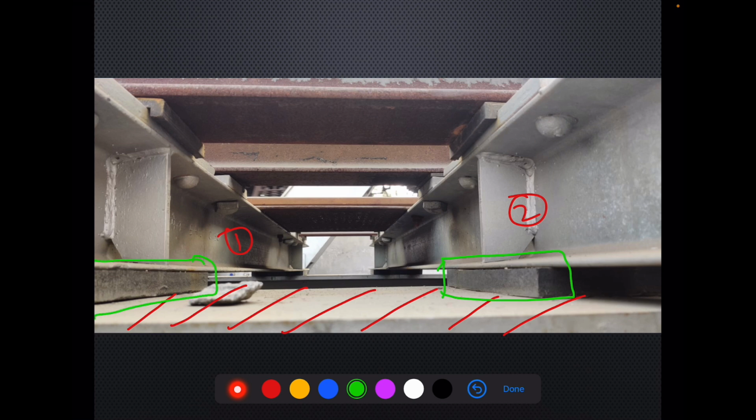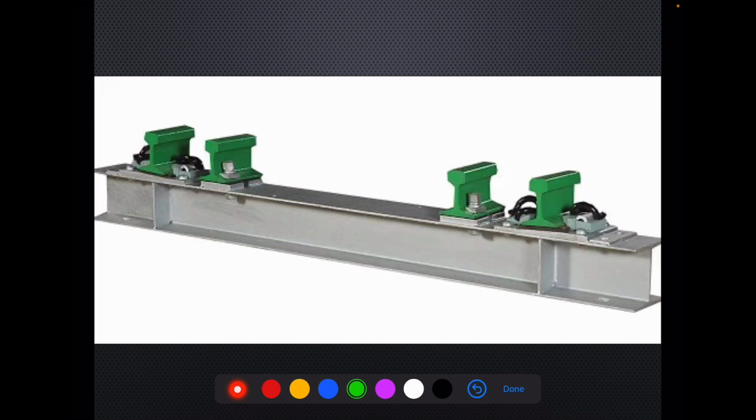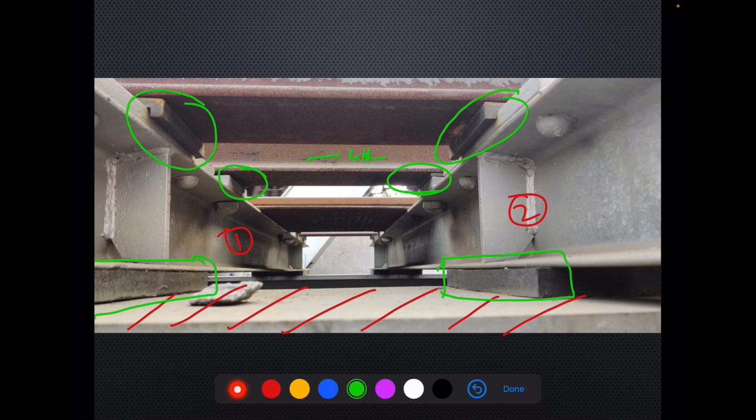Okay. Also between the running rail and channel sleeper, these thicker rubber pads have been provided, and this one is the guardrail. See, a small rubber pad of approximately 6 to 7 mm has been provided over here also. So this was all about steel channel sleepers, right?